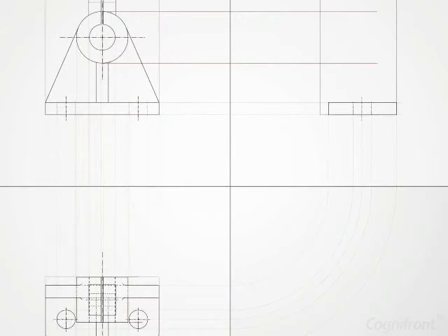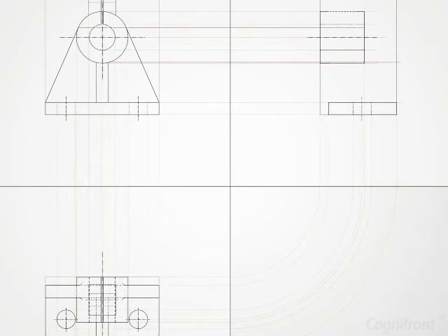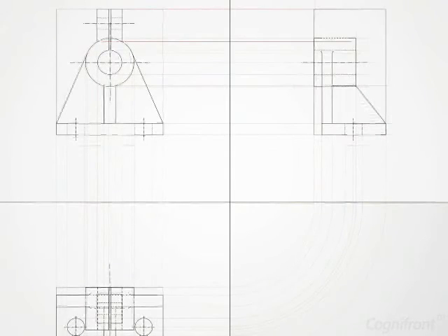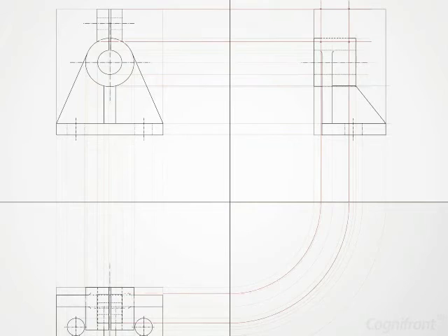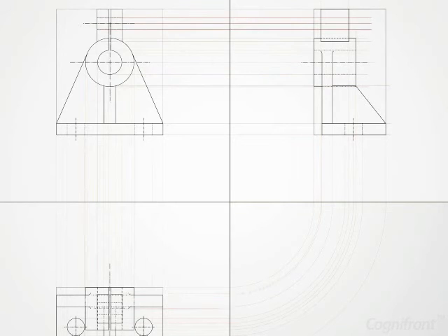Let us now draw the rectangle of the cylinder. The cylinder has a hole, so its dotted lines are visible. Observe that we have dotted center line for this hole. Then generate ribs connecting base plate and the cylinder. Next, the block on the top of cylinder should be generated. Also, observe that we will have to show hole that goes through this block.